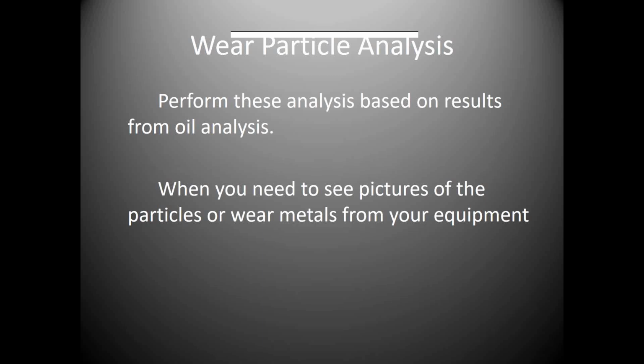One of the things I did at the plant I was from was buy a little digital microscope. If you go online and search for digital microscopes, I bought one that only cost $400. It goes up to 400 power, adjustable from 50 to 400 power. At 100 power, my technicians would put a drop of oil under the microscope, and we could actually see some of these things in our oil without sending it to the lab and without paying $50 or $100 for that analytical slide.